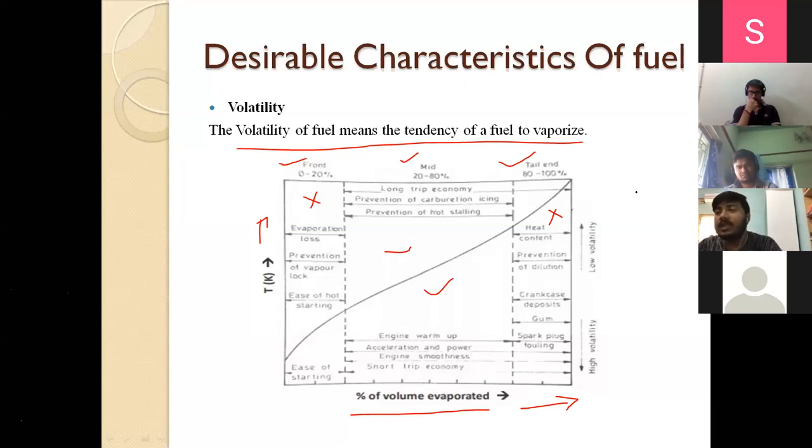Whenever this mixture goes to the contact portion of the piston and the cylinder surfaces where the lubrication stays, it will dilute the lubrication. If the lubrication is diluted, it loses its lubricating property. That means the friction will be more between the piston and the cylinder surfaces in contact, which will affect the efficiency, increase the friction, and lower the lifetime of the piston and the cylinder.